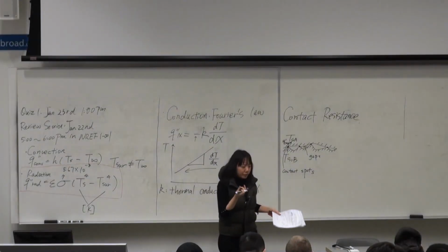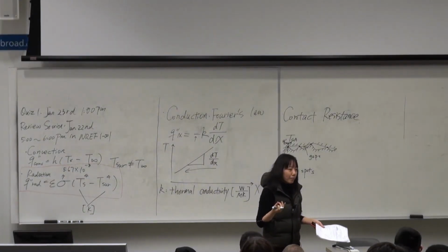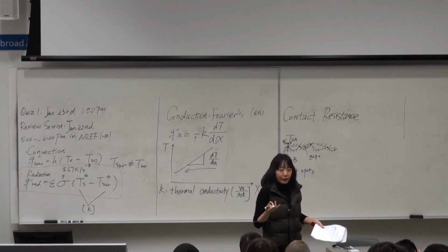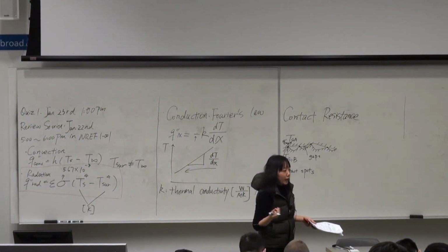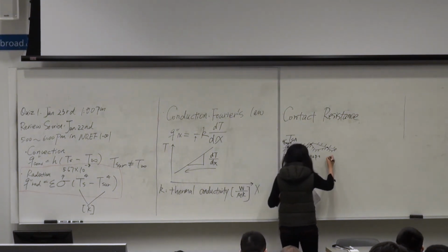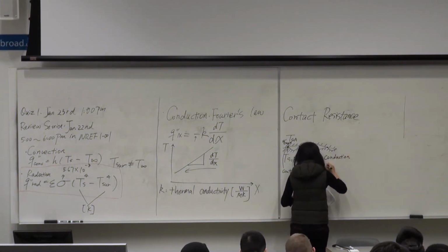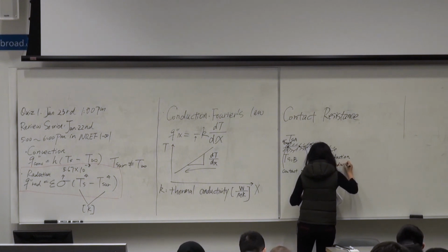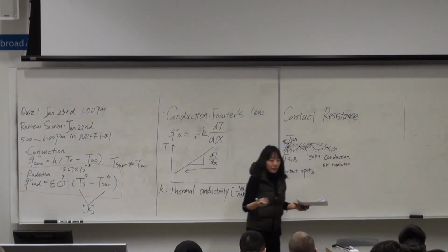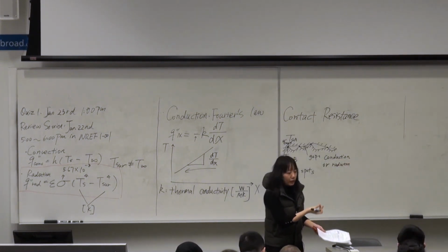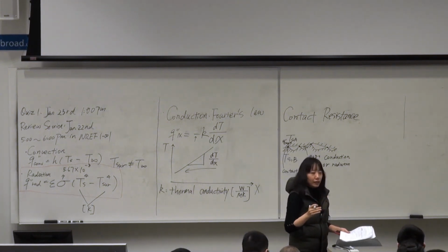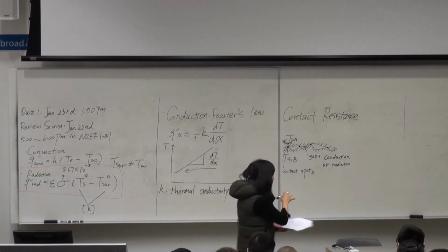For those filler fluids, it can be conduction, or radiation when the temperature is super high. Because the fluid stays still within those gaps, convection does not play a dominant role here.